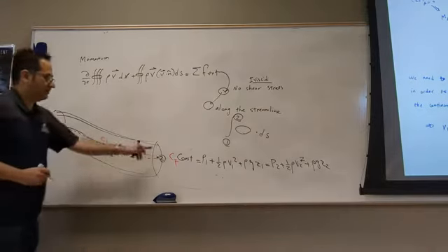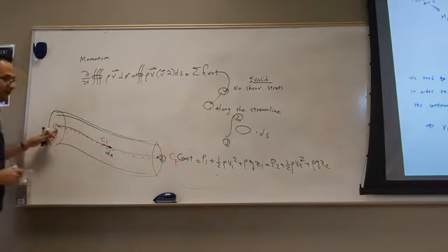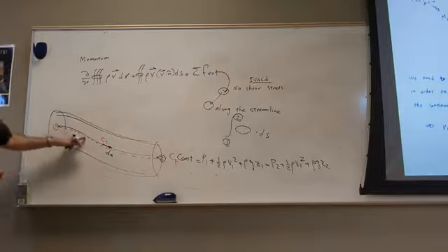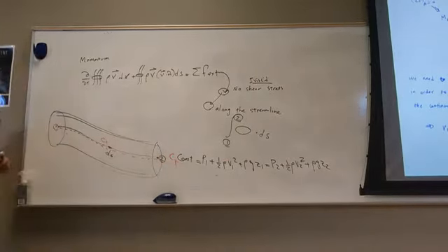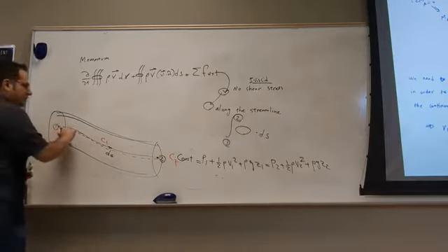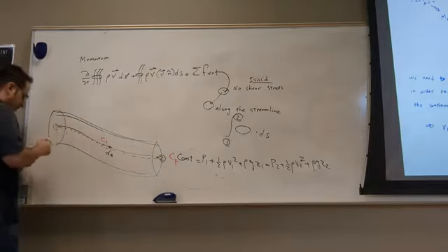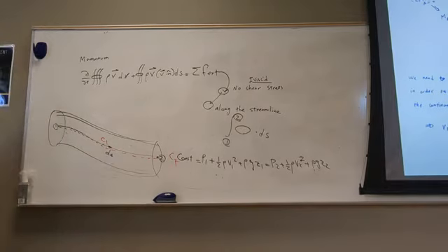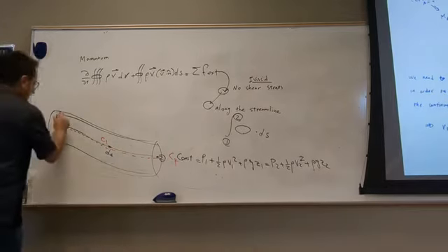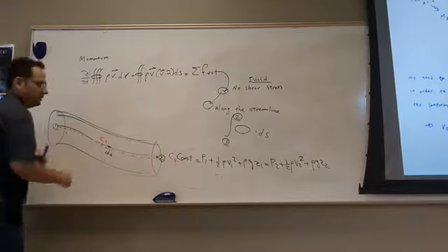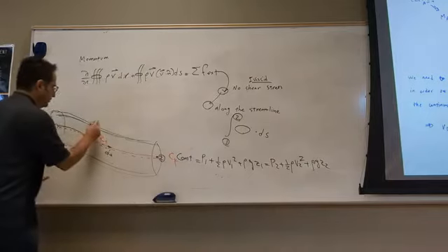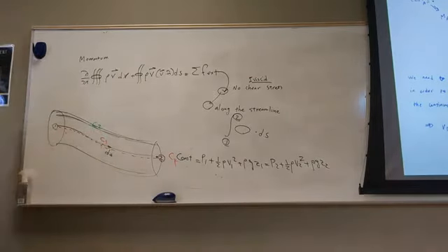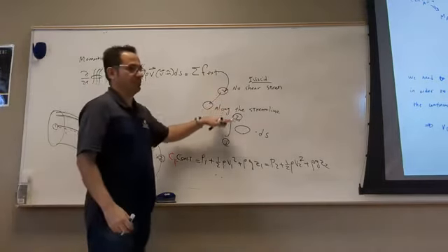That means P1 plus half rho V1 squared plus rho g Z1 is equal to the same sum anywhere across this streamline. But if you go to another streamline, for example the one a little bit upward here, again you can do this line integral, but the constant you get is C2. They are not necessarily the same, based on this assumption.